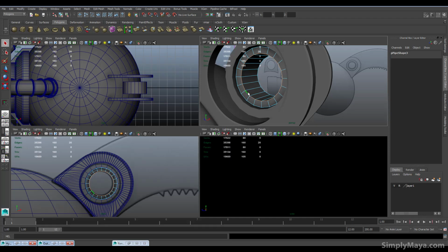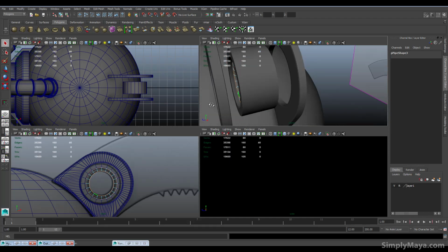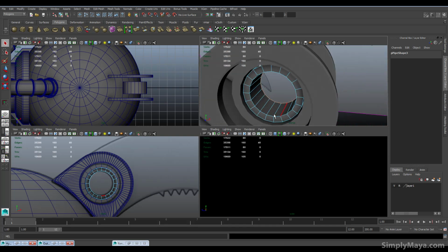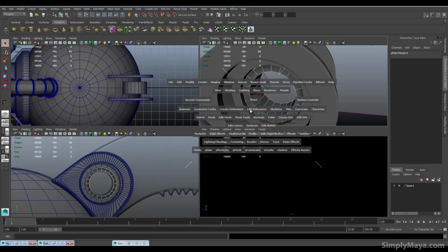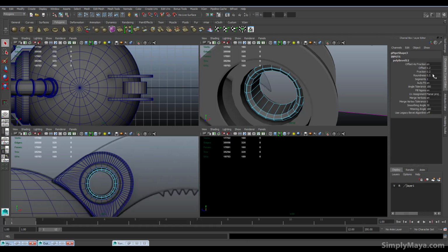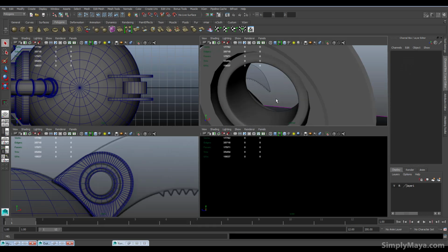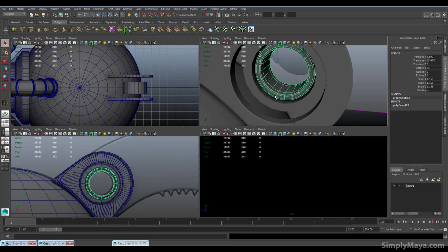And I think with these pieces, we're going to be absolutely fine because they're going to be so small. I'm pressing B to turn off soft selection. We're going to be absolutely fine just to grab them, bevel them, and then smooth them. So edit mesh, bevel, and that's too big. So fraction 0.5, that's fine. Actually, maybe a bit bigger, 0.8, and segments up to 2 because we're going to smooth it. And let's smooth it, and that will be perfectly fine for this kind of operation.